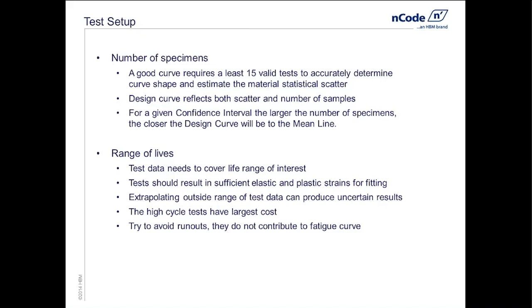The thing we never want to do with these curves, since we're fitting this curve through test data, is extrapolate, because extrapolation is very unpredictable. The curve has been defined by the test data. Areas outside the test region basically have no control. And so we want to ensure that we're never extrapolating from that curve. We'll see that in just a second.